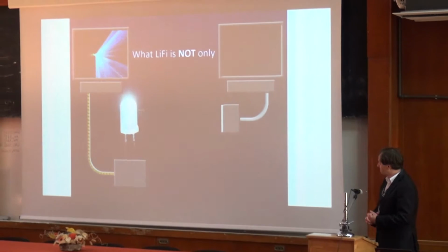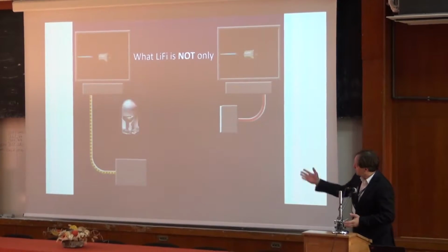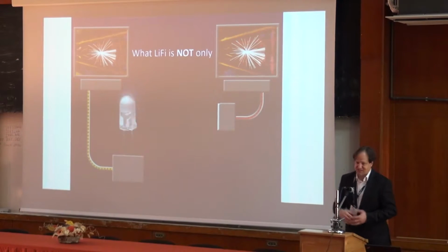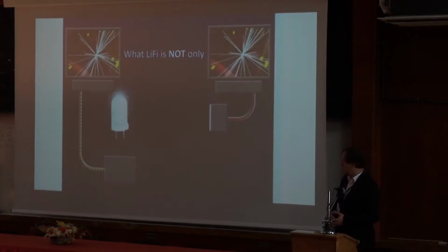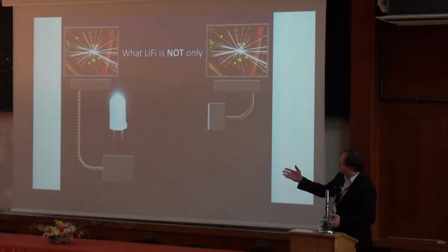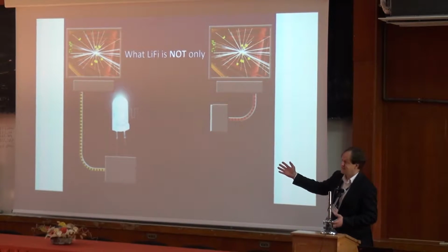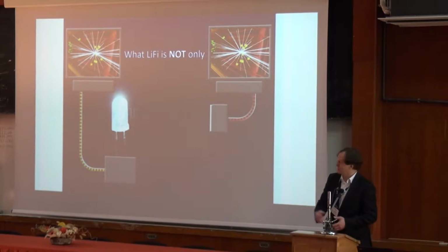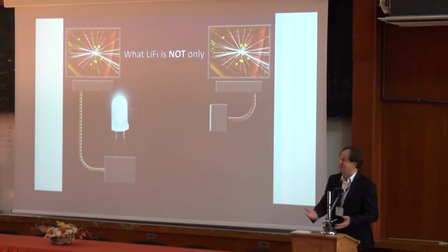First of all, we use some digital content that we have on a tablet or a computer, and we have a connection to an LED light source that has a gray box, and that gray box has some electronics in order to convert AC signals to DC signals. So what we do is we add additional electronics, a microchip, in order then to encode a binary bit stream into intensity variations of the light source. In that case, it's on-off keying, a simple way to transmit a 1. When we turn it on, we want to transmit a 1, and we turn it off when we want to transmit a binary 0. Very simple.